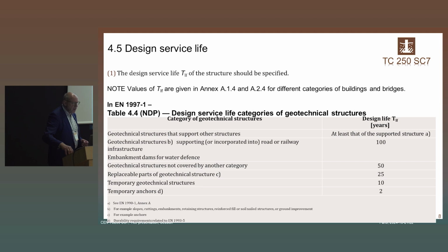Design service life. Design service life is specified in Eurocode EN 1990. They have monumental buildings, I think 100 years, and normal buildings 50 years. We have our own design service life for geotechnical structures, made in Eurocode 7, and that fits in the EN 1990 philosophy.